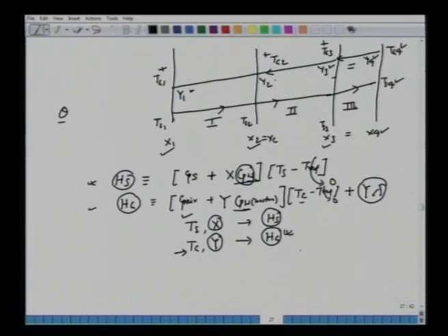Okay. Let's make note of certain other properties which are given to us. So what is the data? Some thermodynamic and thermophysical data are given to us. Ky, the mass transfer coefficient, is 150 kg per meter square per hour. A prime, we said, is the specific effective area of drying. For the solid, this is 0.65 meter square per kg dry basis.